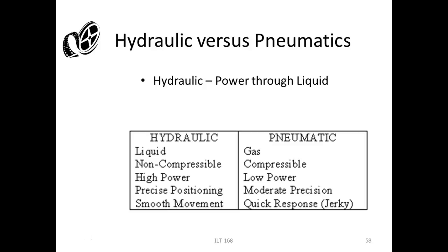Hydraulic power through liquids. Well, let's look this over. So hydraulics uses a liquid, which is non-compressible. That's a term that we use, but that's not exactly true. It's just that it compresses so little. It's almost impossible to get a fluid that doesn't have air in it at all, right? And of course, air is compressible. So saying a fluid is non-compressible is a term that we'll use in this class, but it compresses so little that we couldn't measure the compressibility of a liquid.